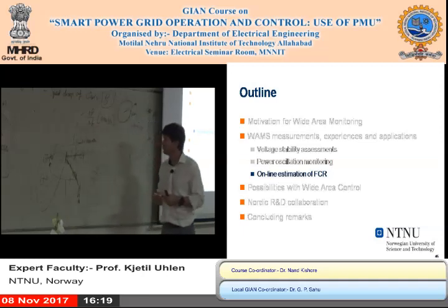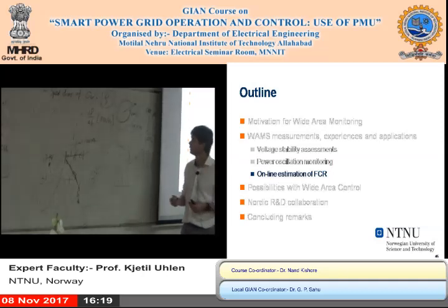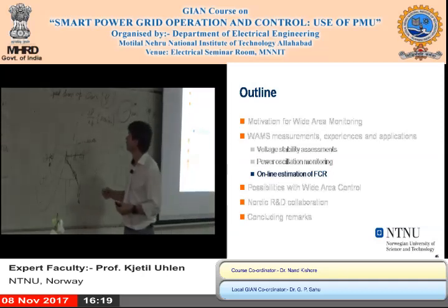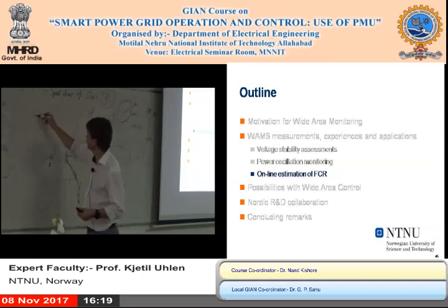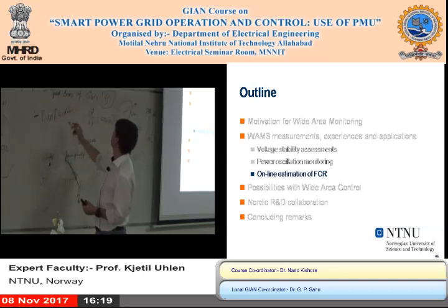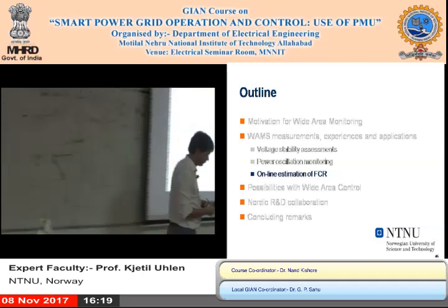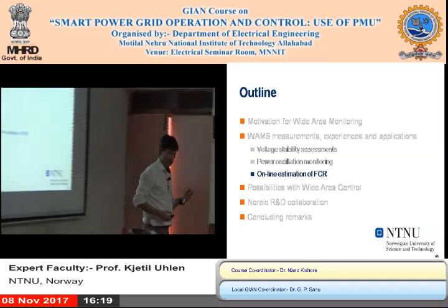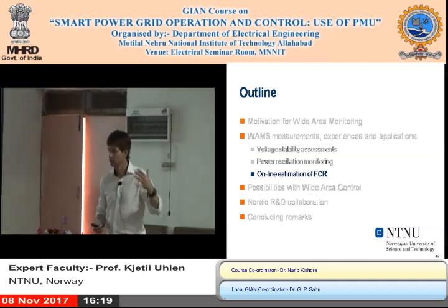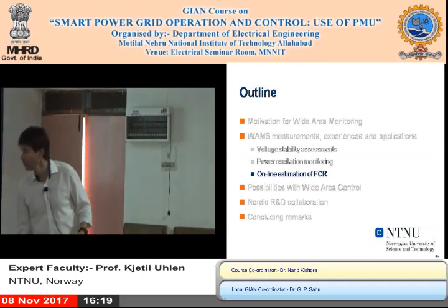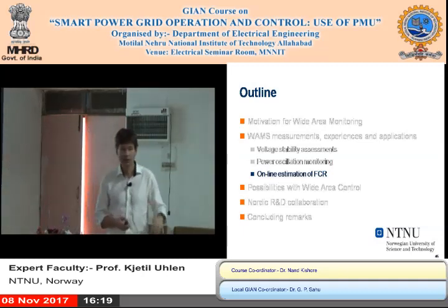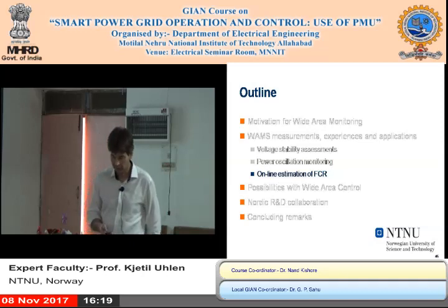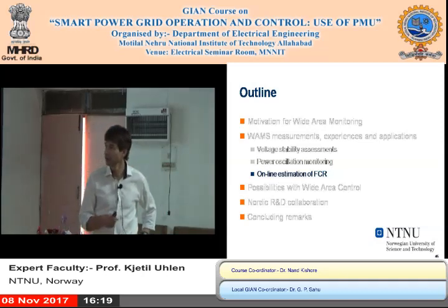You can measure directly the megawatt per hertz. But in addition to that, the steady state is one thing, but what is the bandwidth? These are the questions that are interesting for the operator to know. Do the generators provide the controls that they are contracted to do? Do they do what they are paid for?